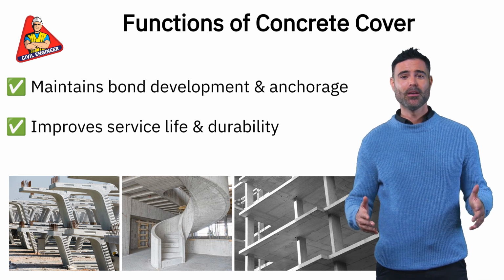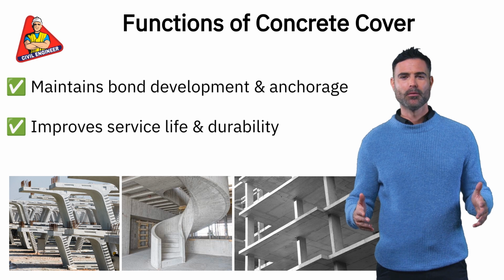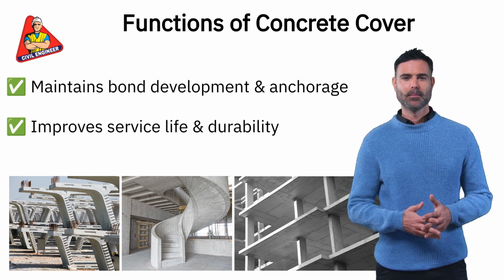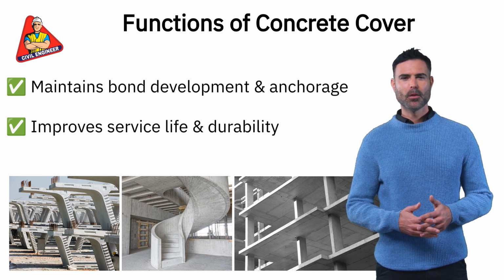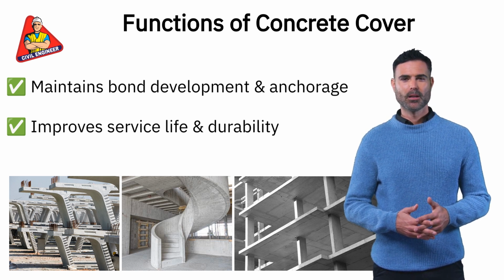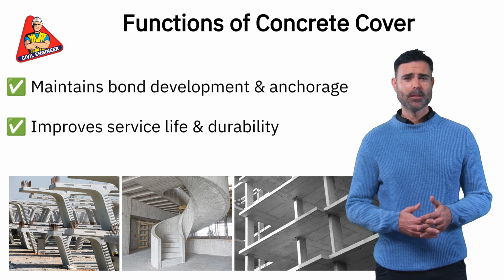It ensures sufficient bond development length and anchorage of rebars, critical for flexural and axial capacity. Adequate cover ensures long-term durability, especially under Class B2 or Class C exposures, preventing premature deterioration of reinforced concrete elements.